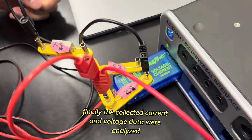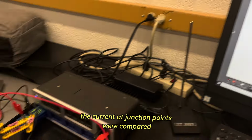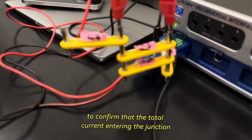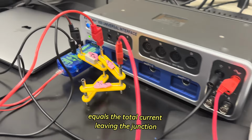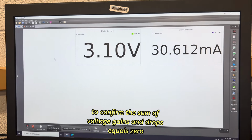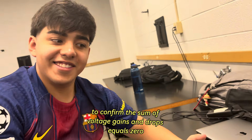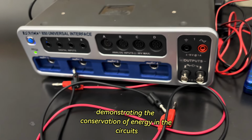Finally, the collected current and voltage data were analyzed to verify Kirchhoff's rules. The currents at junction points were compared to confirm that the total current entering the junction equals the total current leaving the junction. Additionally, the voltage values across each loop were added together to confirm the sum of voltage gains and drops equals 0, demonstrating the conservation of energy in the circuit.